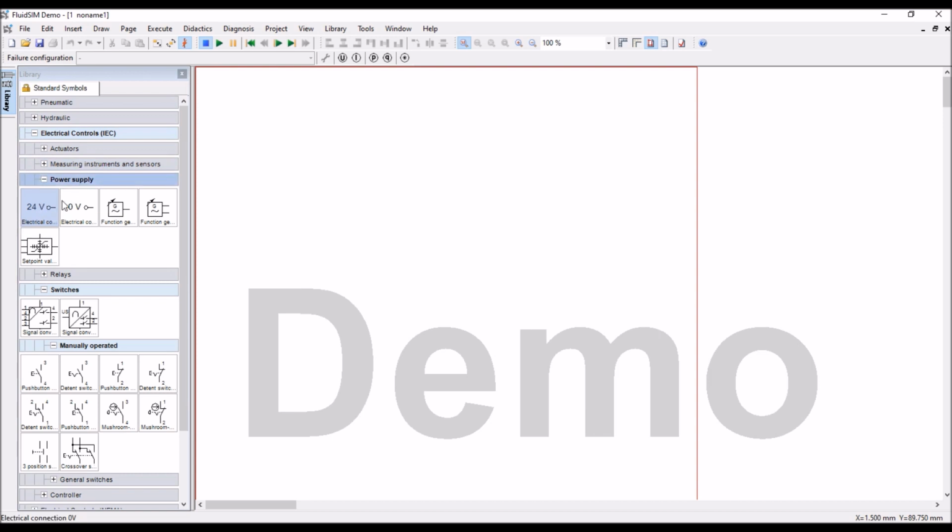Okay, first drag and drop power lines. It is also suggesting this is the alignment, perfect alignment. Then drop it. Now normally open push button, go there and drag and drop onto the screen. It will indicate the alignment, red, it's okay. Then drop it. Then connect the 2 points here,